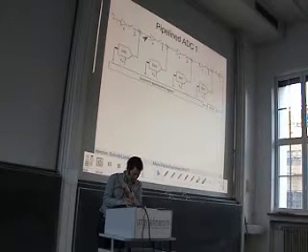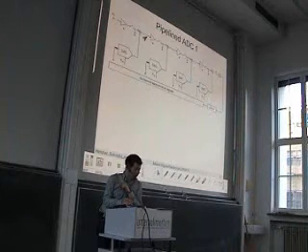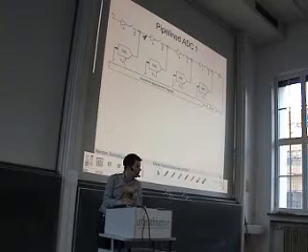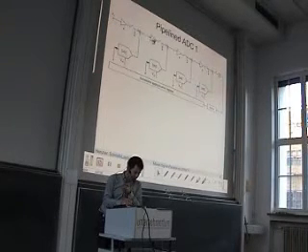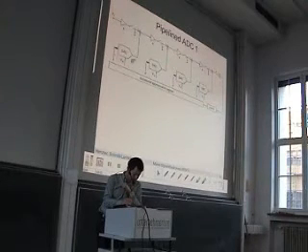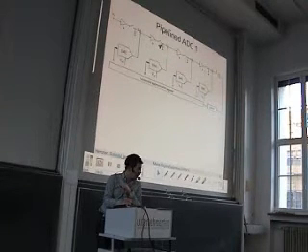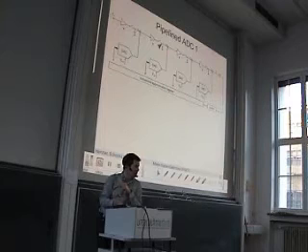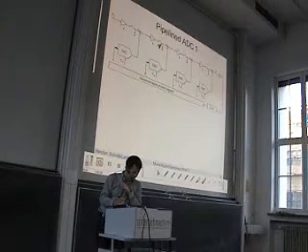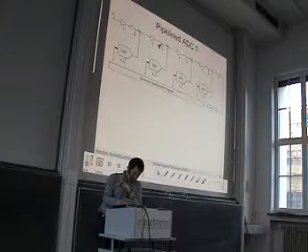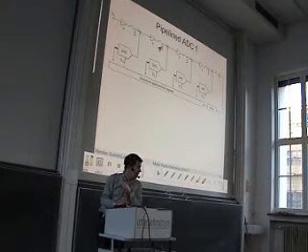Then we cannot keep it constant here in a pipeline concept because we want to process new data from the input. So we have to sample the result from the first stage again to keep it constant for all subsequent stages. This means that we need these additional sampling elements.